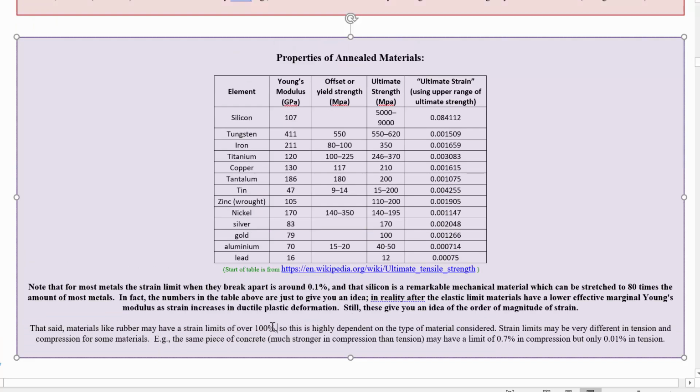Like you can imagine taking an elastic band and quite easily stretching it to double or even triple or perhaps quadruple its length. And it's not about being shaped like a spring or something like that. Those sorts of materials can have much higher strain limits, but they're very, very special and used for the very large strain limit that they can have and the large elastic response of them. For a typical metal, an elastic response that is much lower than that is more typical.